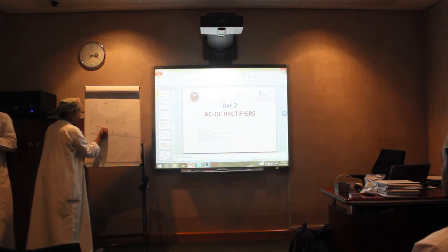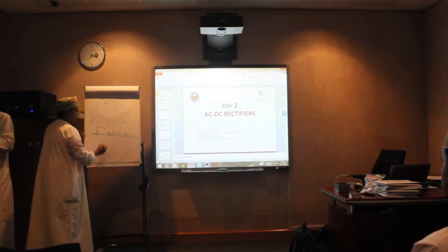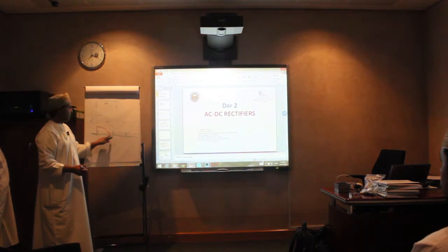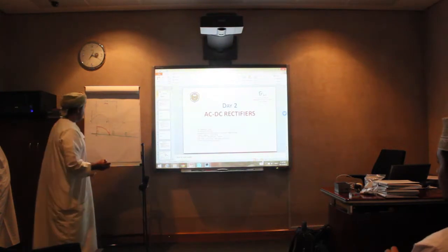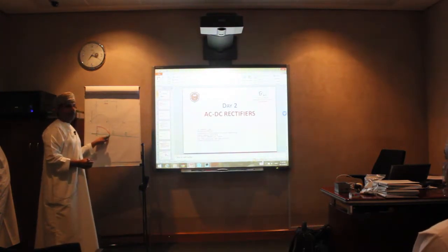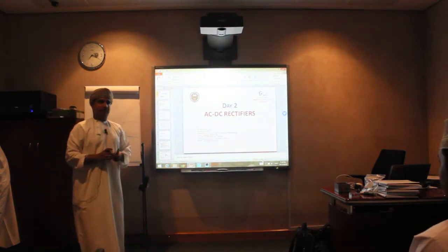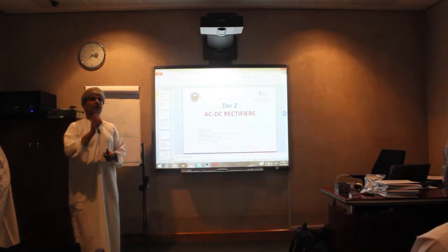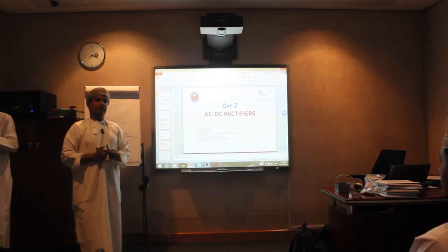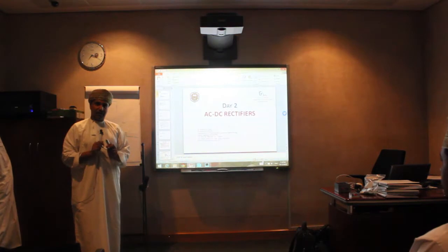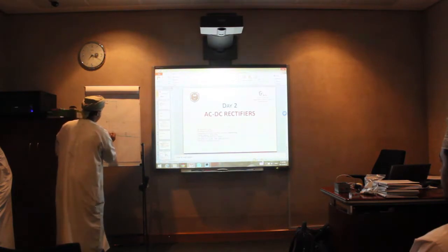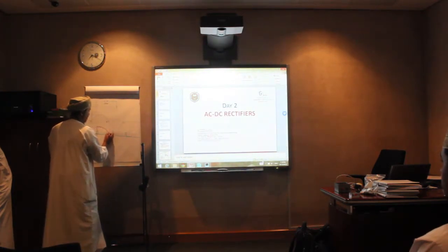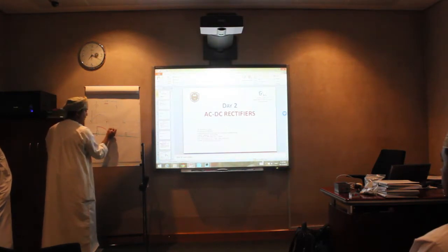and then will continue until the current goes to 0 across the thyristor, or sometimes called the current less than the holding current, practically. When we send the signal, we don't have to continue sending the signal to keep it on, until the current reaches 0. Practically, it should be less than the holding current, not exactly 0, a little bit above 0. And then it will stay 0, waiting for the next signal.